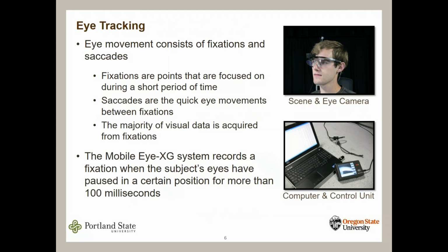In addition to the driving simulator equipment, we're also interested in the visual attention of road users. For this particular experiment, we were using eye tracking equipment that was head mounted and monocular in nature. That means that our users were wearing a pair of sports goggles with 2 cameras mounted to them. One camera was called the scene camera that captures a visual record of everything the driver saw, pointing away from the sports goggles. The second camera uses infrared light beams that are reflected off the pupil of the driver's eye.